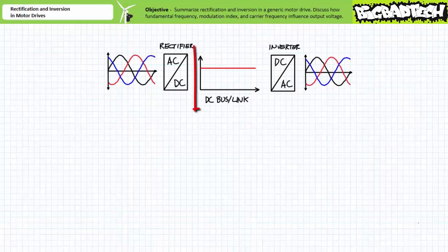For this reason, motor drives are somewhat mistakenly referred to as inverters, which actually only describes one half of their purpose. The DC voltage in between the two related power electronic stages is sometimes known as the DC bus or the DC link. The DC bus can store tremendously large values of DC voltage and must be treated with caution. For example, a motor drive operated on 120 volt line to neutral and 208 volt line to line light industrial three-phase AC might have an average DC bus value of over 280 volts.